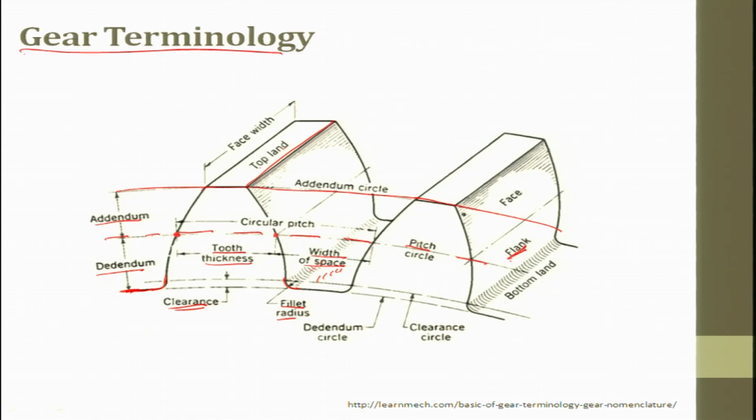Now, if you look very closely, there is a lot of complex geometry involved. To generate this geometry through machining, we always use the concept of involutes, which we study in engineering drawing. That is used when meshing happens between the tool and the workpiece, or you can generate it by milling, by cutting these slots in between. You have to understand all this gear terminology; it is very important.